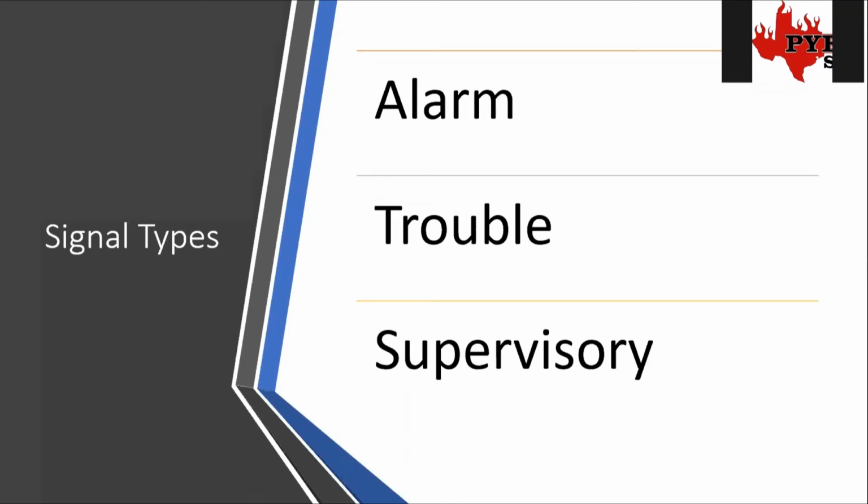This is also the one that calls the fire department as well as the end user, the customer, the owner of the building, whoever. That's the alarm. It means there's some kind of smoke or water flowing, or someone pulled a pull station, or something went off that's saying, hey, there's a fire in the building.